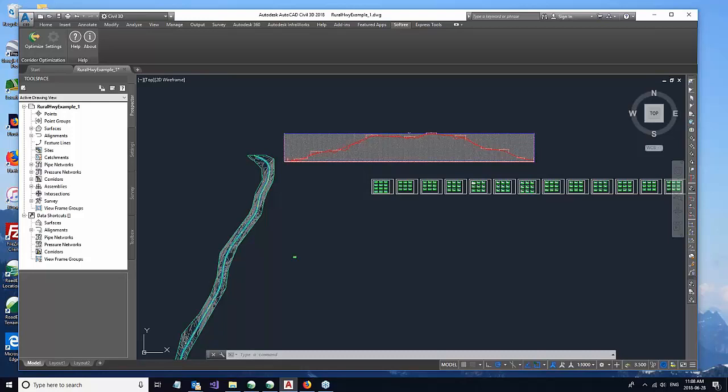The best type of project is an alignment that you can move around, or that the optimizer can move around looking for a good solution. So it'll save you all those trial and error iterations of moving around, looking at your quantities, looking at the movement, all that sort of thing. So in general, more rural design, unconstrained, and obviously a design that's got some significant costs, earthwork costs, is a good candidate project for Softree Optimal.